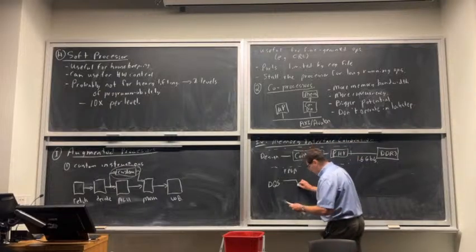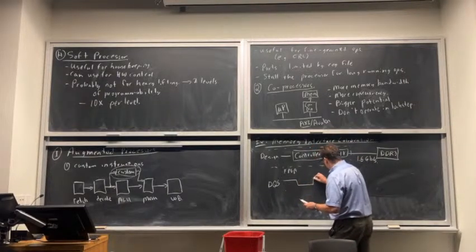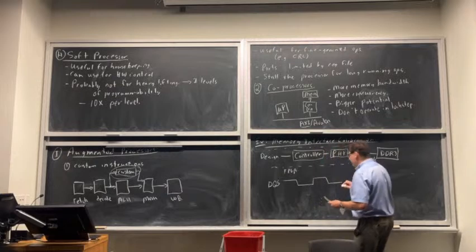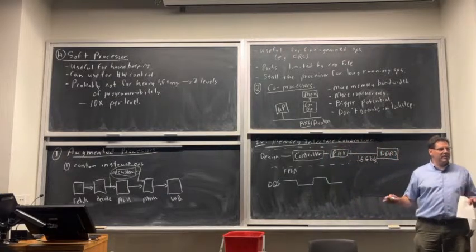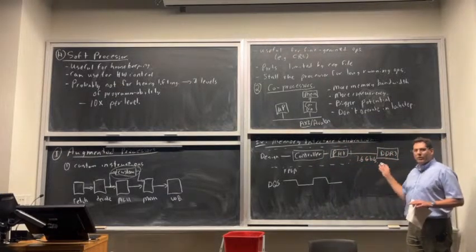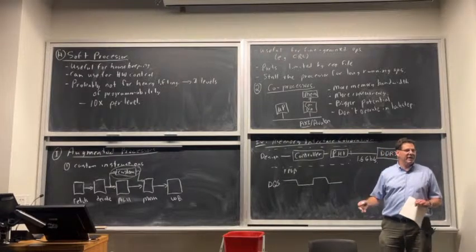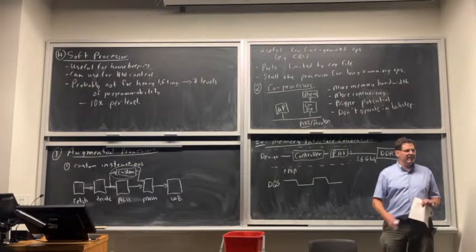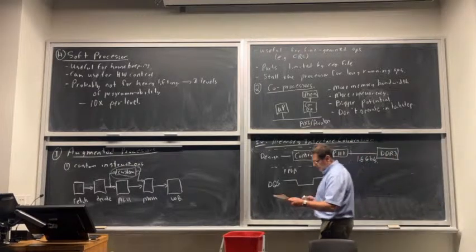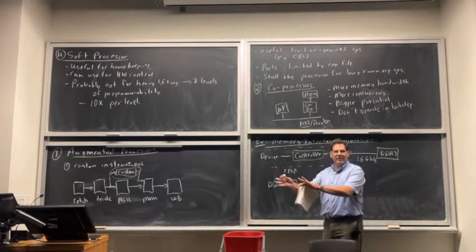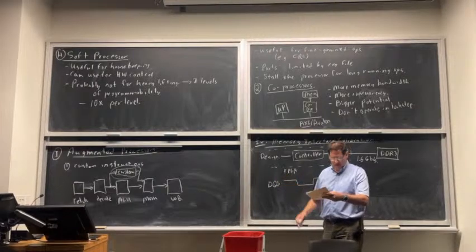So what does source synchronous mean? It means you send the clock with the data. There's no notion of one clock that everybody's listening to for these I/O transfers. You send a clock and you send some data with it, and you use that clock to sample that data. This can be done at much, much higher rates because they're traveling just alongside each other, so there's not nearly as much skew.